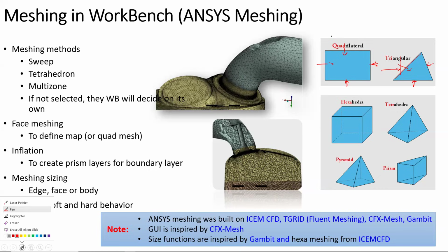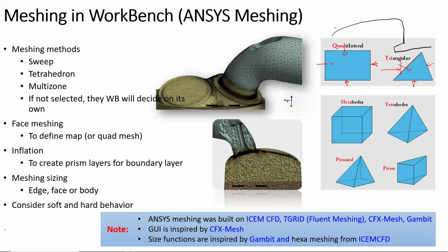See, if this is my geometry, then having the quad elements, on this corner it has to be very controlled here, otherwise quality can be low. And here, maybe one element is like this. So here, how do we divide the element, how do we put the element here? But if you take a look at the triangle, the triangle can adapt to any geometry very well.